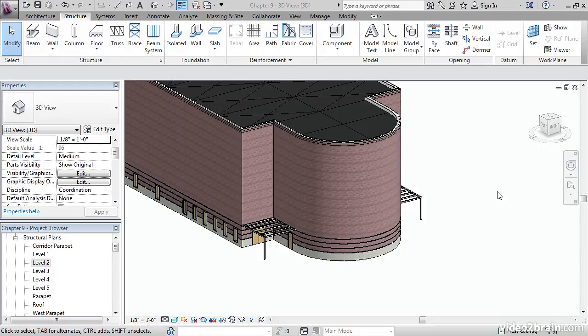You can add them in one by one, point by point, or you can actually define a space, define the framing members and the spacing, and let Revit automatically fill the void. The objective of this lesson is to do both. First, we're going to attach some columns to the roof and make some other adjustments. Then, we're going to add the perimeter framing, then add beam systems to fill in the space.